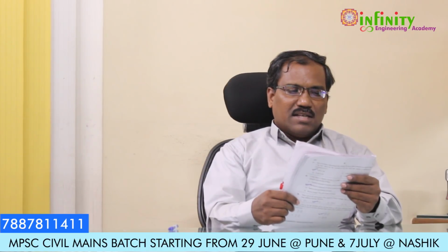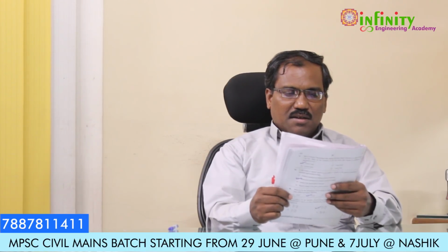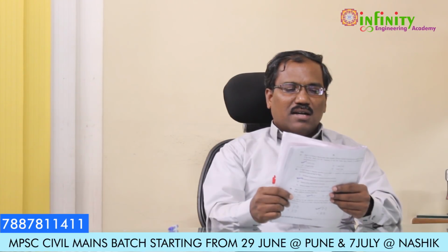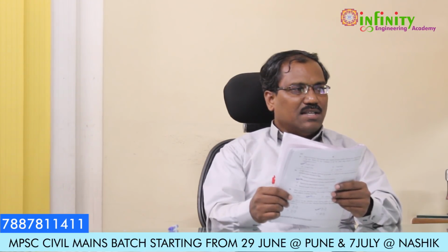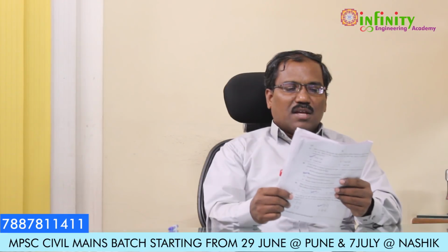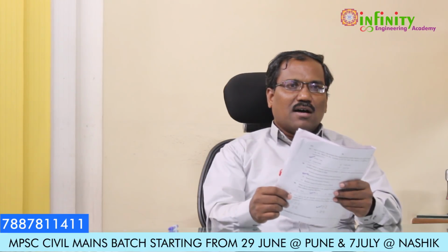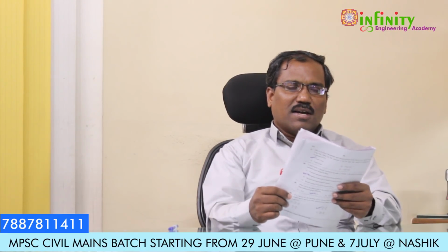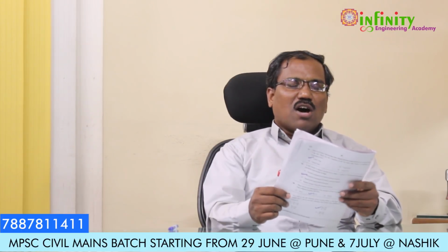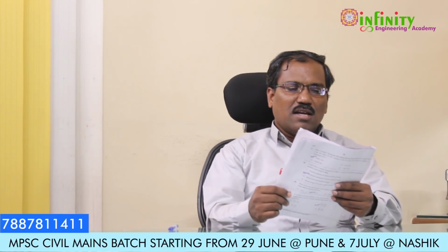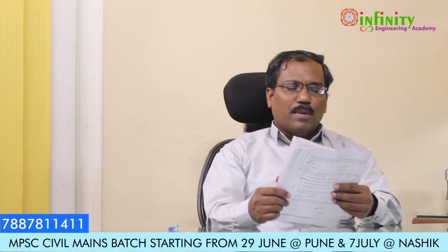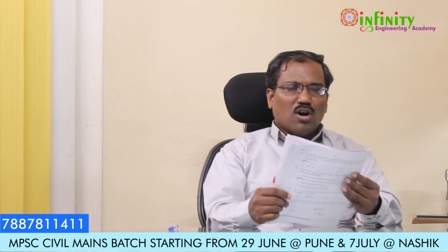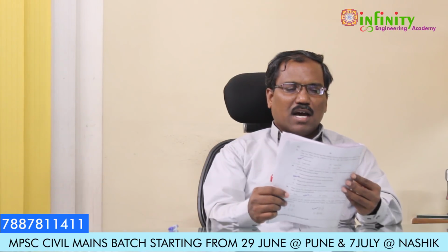And the next one is, okay, what is the carbon content of the mild steel? The mild steel is called the plain carbon steel, also called the low carbon steel, because in plain carbon steels we have the classification based upon the carbon content: low carbon steel, medium carbon steel and high carbon steels.